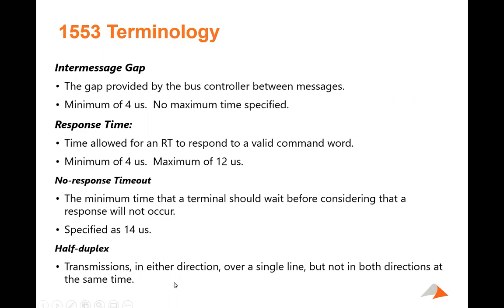And of course, it's a half duplex bus. I guess I should have mentioned that just a little bit earlier, but you probably caught on to that since the bus controller is initiating all of the communications, the communication message goes across, responses come back. Don't have multiple messages, like you wouldn't send messages on the A bus and on the B bus and be expecting everybody to be responding to it. That actually would be called a superseding command. And it can be done, and sometimes people use it as a recovery methodology. But 1553 is a half duplex.